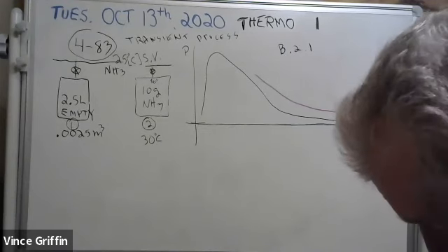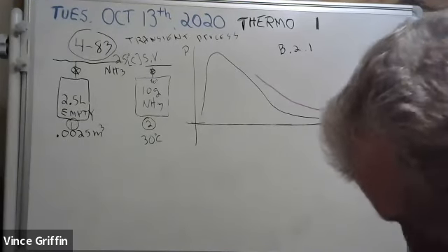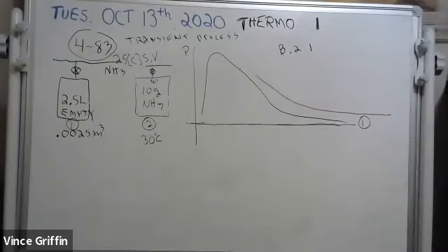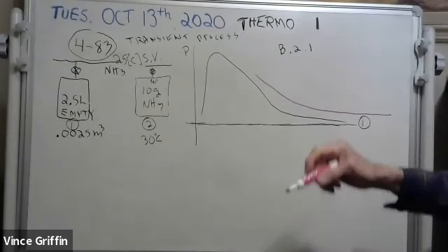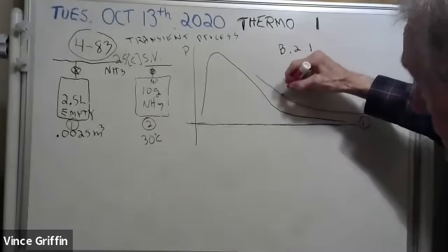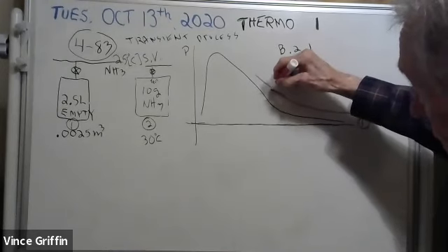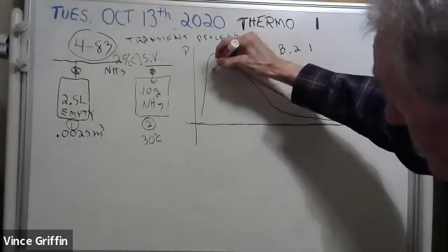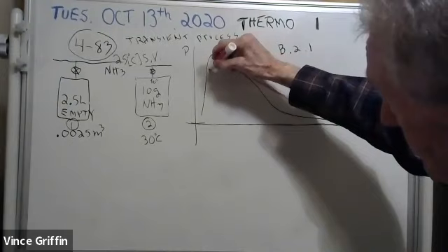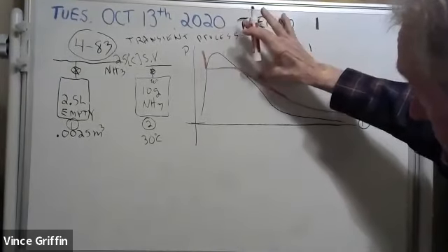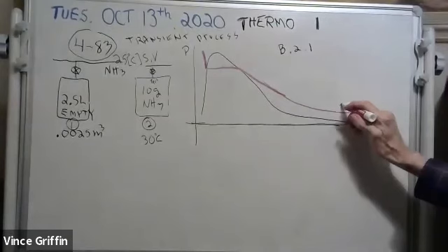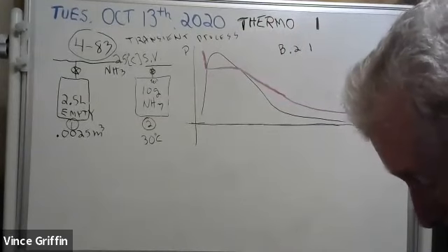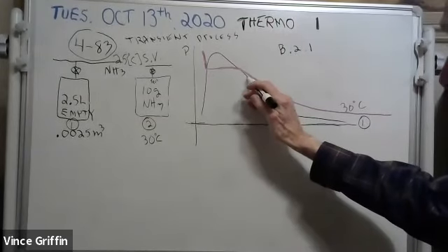Well, we don't know what the final pressure is. I tell you what we do know. The ammonia coming in is saturated vapor at 25. See, this 30 will come up here someplace, hit this, go over here flat, and go up. There's your 30 degree Celsius isotherm. But what we're at is 25, and it's right about here.